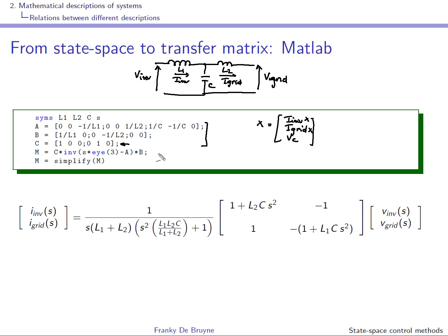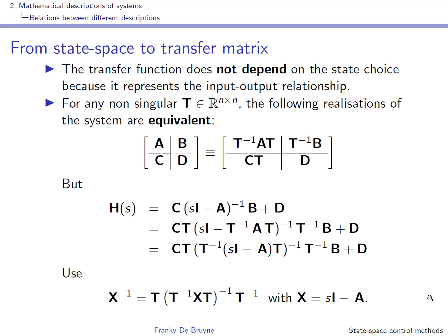And if you compute C times (sI minus A) inverse times B, and you can do this in Matlab using the symbolic toolbox, it will do all the hard work for you, and then you simplify, you will see that you come up with the transfer matrix, and this comes in handy if you analyze systems.